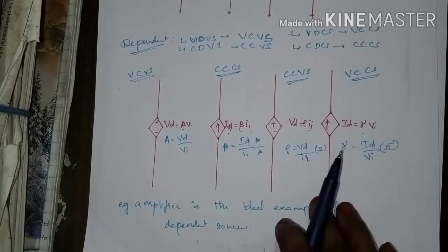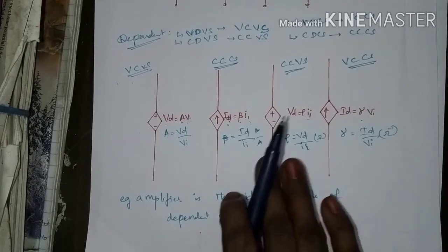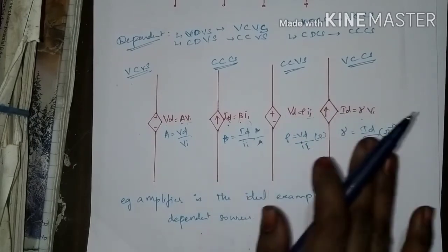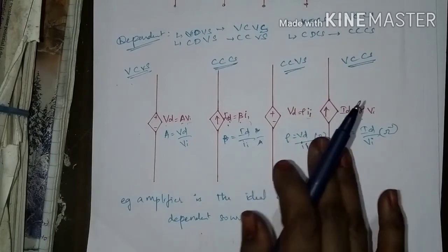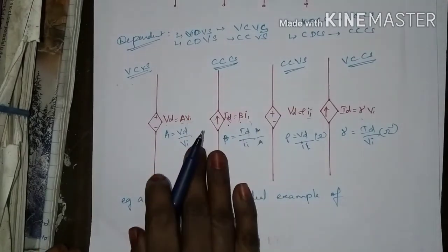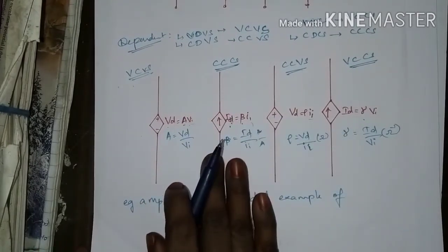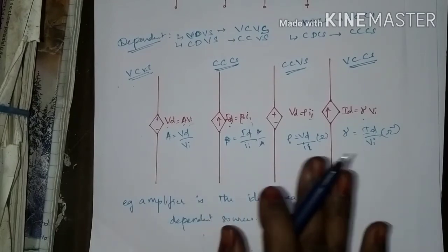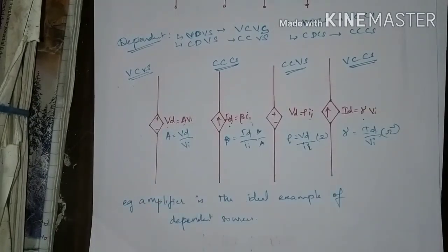Once the dependent sources are located in a circuit with the definitions for the controlling currents and voltages, the circuit analysis must proceed as always. KCL and KVL still apply, and all the techniques derived from these also still apply. The voltage divider, node voltage method and loop current techniques are all unchanged, and the dependent source is simply included in all these methods.